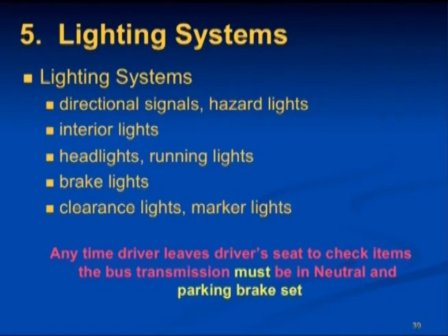We're checking directional signals, hazard lights, interior lights, dome lights. The headlights should be checked on low beam and high beam. Make sure that the running lights are clean. Make sure that your brake lights are clean and light up when the brake pedal is depressed. Make sure your clearance lights and marker lights are the proper color, yellow to the front of the rear axle and red behind the rear axle.